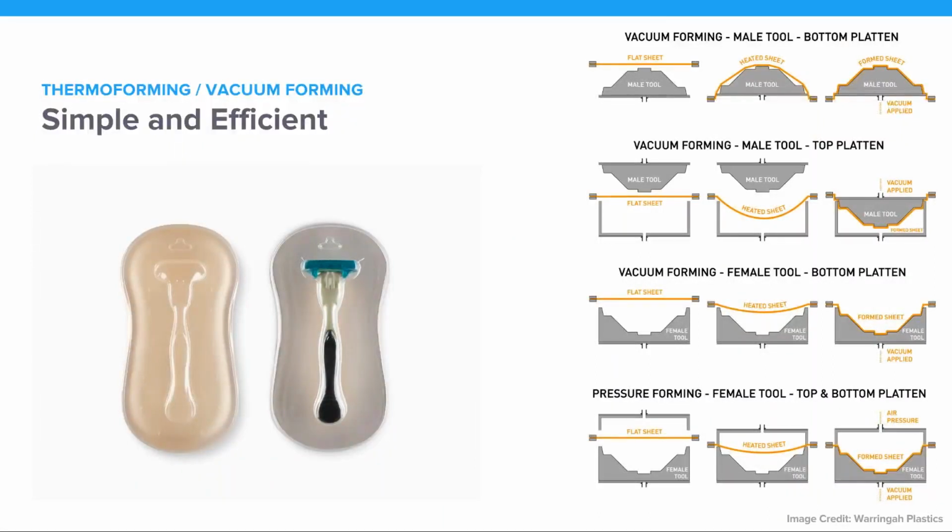They're slightly different. It was originally developed in the 1940s to produce aircraft canopies that didn't have any blemishes and army relief maps, so you could have a little scale model of the hill you're supposed to assault. Thermoforming is the first process that was developed. The way it works is you have two halves of a mold and a heated sheet of plastic. You press the sheet of plastic between the two mold halves and you come out with a part. Vacuum forming uses only one half of the mold, and it uses suction or vacuum to pull the plastic down over the part or the mold.